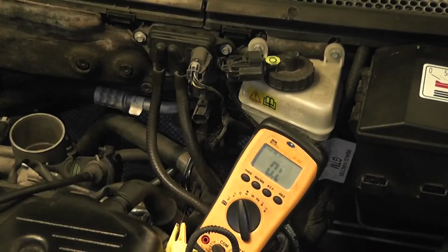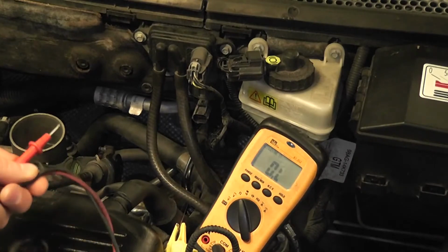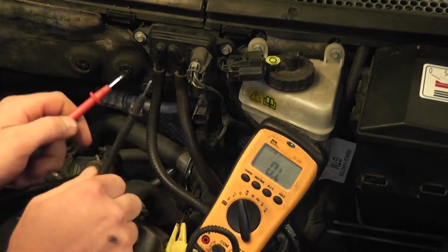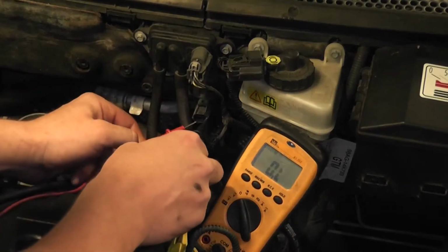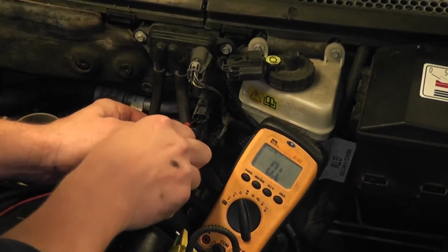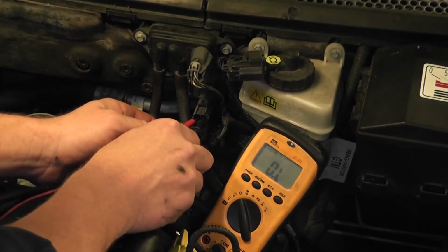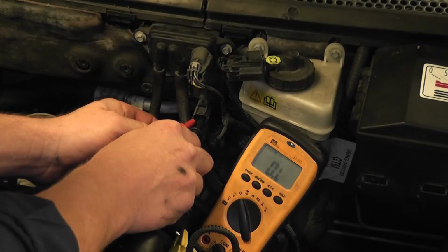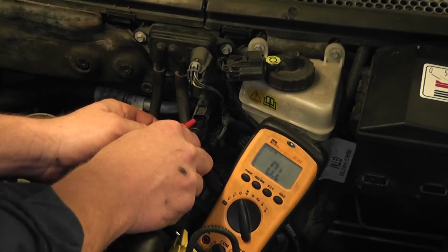Okay, I'm doing an ohm check on this solenoid. If what we did so far is correct, when we do this measurement, it should stay OL M ohms, which is the scale I'm on right now, which is a mega ohm scale. So I want to reach in and touch these two pins. So touching the two pins, as you can see, that confirms our call. This solenoid is open.